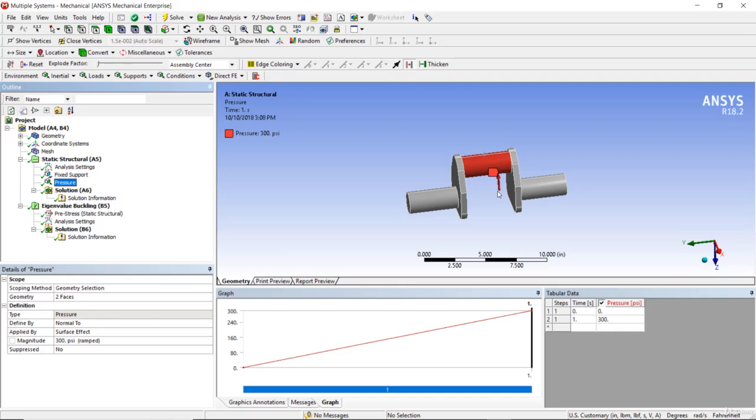This structure is going to buckle in mode number 1. So if I reverse this direction, let us say instead of applying like this, if I just apply it towards the outside, this particular structure is going to buckle. Likewise, see, getting a negative buckling factor is not an error. It is always possible. For example, if you take pressure vessels, if you take water storage tanks and other sorts of examples, you may have a lot of negative buckling factors.